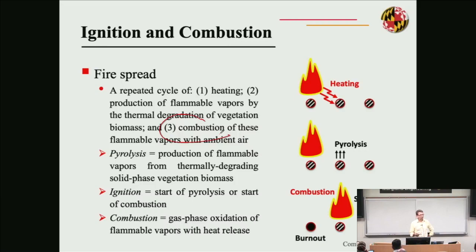The terminology is important. It's not perfect in the fire safety engineering literature. So pyrolysis for us refers to the thermal degradation of solid fuels and the production of flammable vapor. So it's a gas phase change. It's a phase change from solid to gas transformation of hydrocarbons.